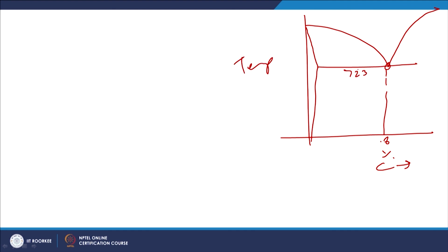Say this is the iron carbon diagram, simple, and this is the eutectoid point corresponding to about 0.8% carbon. Here we have temperature in degrees centigrade, this is 727, this is 910 degrees centigrade, and carbon content here is 0, and this value is also very low, like 0.05.